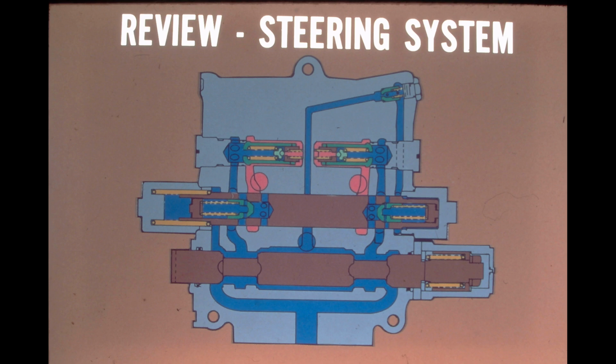The answer to number 1 is true. The linkage is designed to return the control spool to neutral as the machine turns. Number 2 is false. The circuit relief valves block the pump flow from the steering cylinders. Number 3 is true. The circuit relief valves are not adjustable.